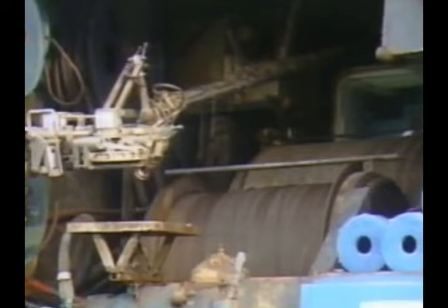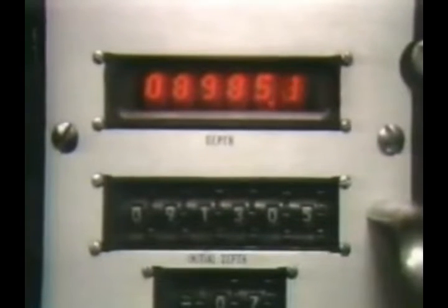The sheave assembly is used to suspend the tools over the well and direct the cable from the truck or wireline unit. Between the top sheave and the rig elevators or crane is a tension measuring device which measures the strain on the cable. Modern perforating and logging trucks include the drum of conductor cable and the winch system to spool it in and out of the well. A depth measurement device keeps track of the tool's position.